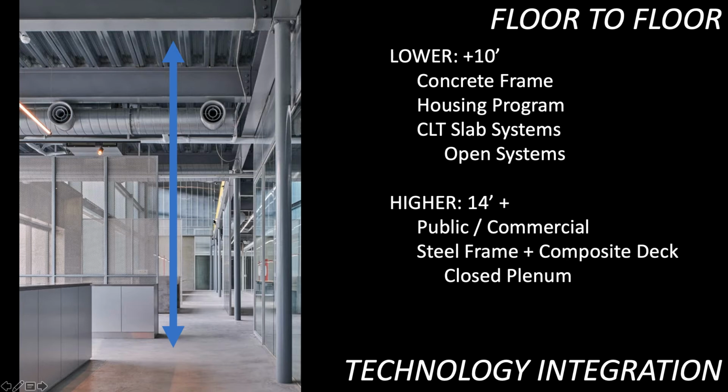When we're looking at the section overall, we usually talk about the floor-to-floor distance. And the floor-to-floor is literally what it sounds like. From the floor above to the floor below, what are those dimensions? And maybe using technologies or even project types that have lower floor-to-floor dimensions and sometimes higher floor-to-floor dimensions. So just a couple of examples. I would expect lower floor-to-floor dimensions if I'm using a concrete frame. In some of those systems, we can collapse out basically this beam configuration. We can go straight from columns to slab, and so we get a reduced floor-to-floor.